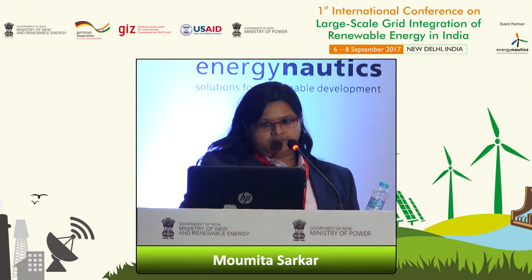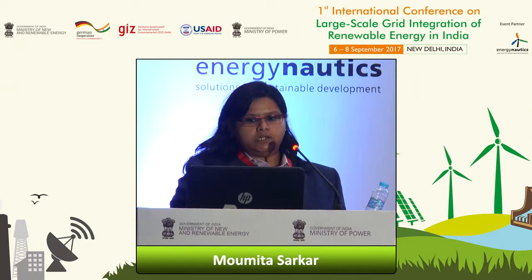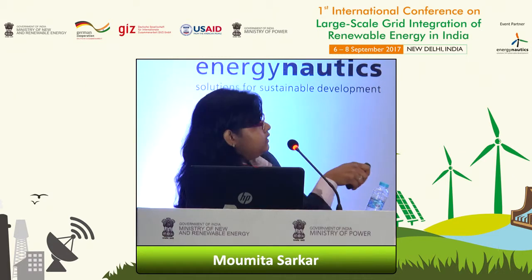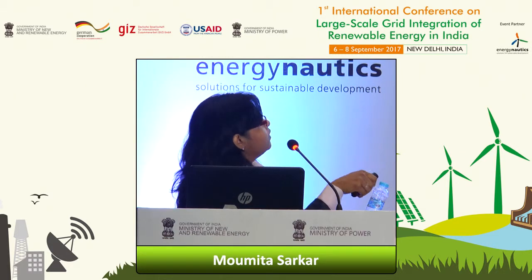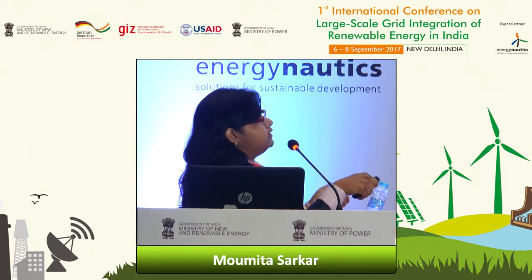So for the transient study, we studied the low voltage ride through. We did 3 studies: one without LVRT, and one LVRT with the Q controller operating in voltage control mode, and the other with the Q controller working in Q control mode.